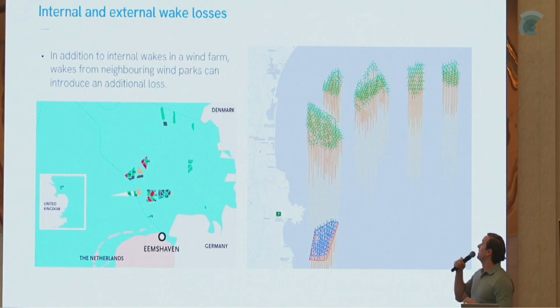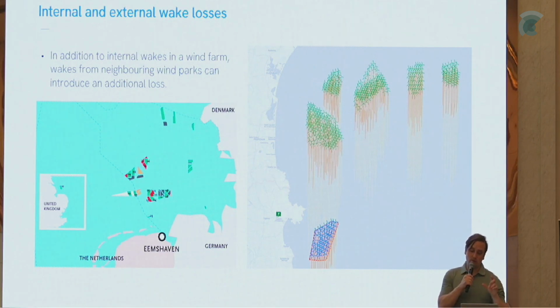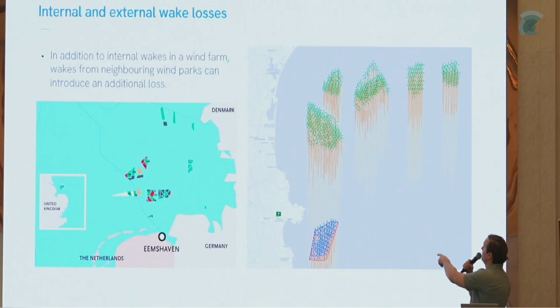Here is a site that we have in the French Mediterranean and the Spanish Mediterranean, just to show you that even though you're planning large wind farms, and this might be very relevant also for offshore wind in Thailand, when you have large clusters of neighboring wind farms, they will also have very long wake tails, as you can see here, that will have an impact on your current analysis. Here, these wind farms are approximately 80 kilometers apart, and they have around 1.5% loss on this current wind farm here in the Spanish region. So it is very important also for the early stages to simulate these impacts.